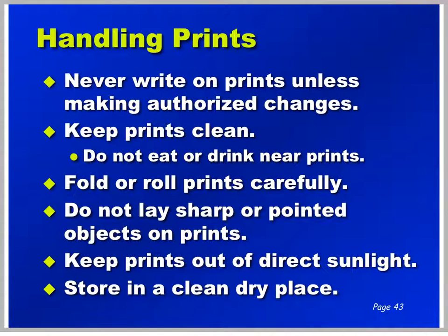When handling drawings, there are a few basic considerations that need to be observed. Never write on the prints unless making authorized changes. I know that sounds a little bit silly, but it makes a big difference later on. Remember, somebody else may come look at this print who wasn't there and may have no idea why you made those marks on the drawings. It should be obvious. Keep them clean.